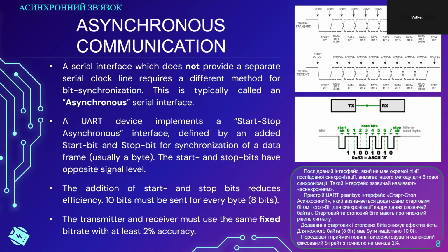Telephone line communication was done through modems, modulator, demodulator units. And the European standard V21 and the Bell 103 standard started out with a speed of 300 bits per second, or baud in this case, 300 bits per second duplex in both directions in one telephone channel.